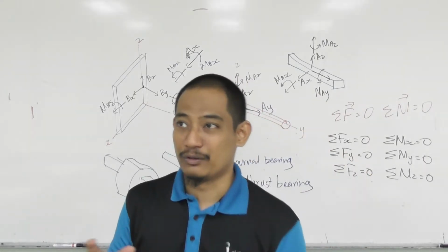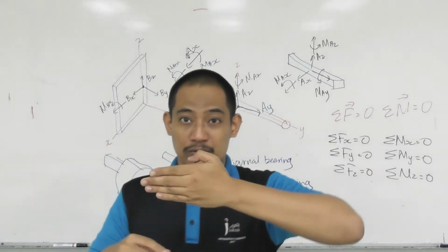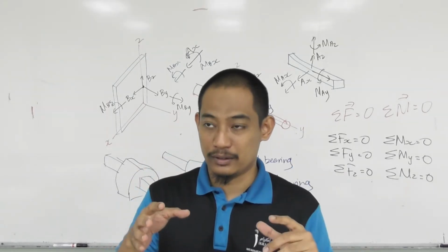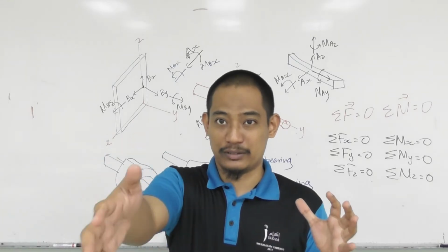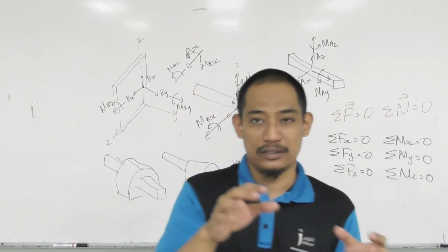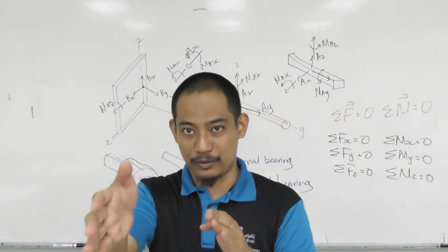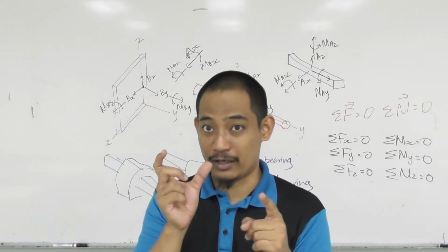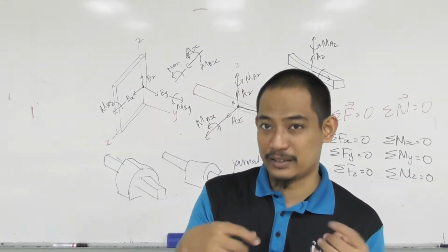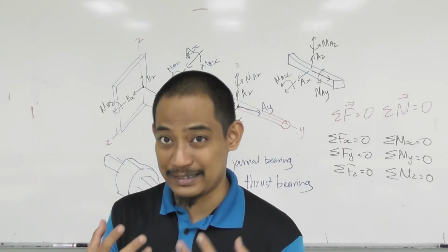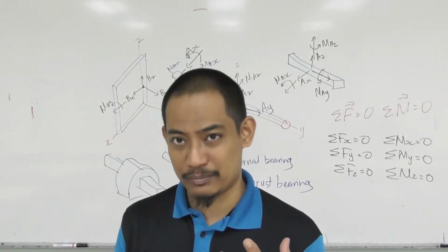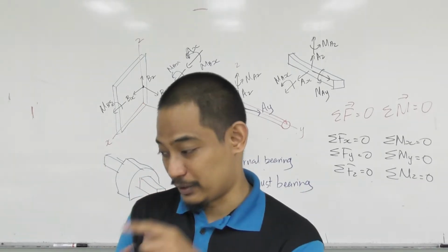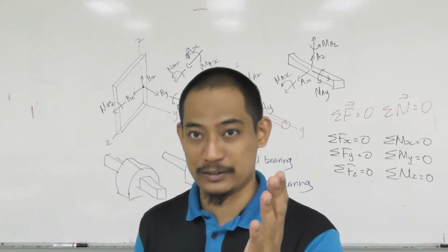How to say this? In 2D, you can take moment about point A or point B or point C, for example. Similarly, for moment about an axis in 3D, you can take it about this axis or this axis or this axis. It still rotates similarly, but about different axes where the distance will be different. So if you use R cross F, R will be different, and the selection can make the solution easier. Hopefully we can have some exercises after this, depending on the type of structure, and when we go into the examples, we will see this.